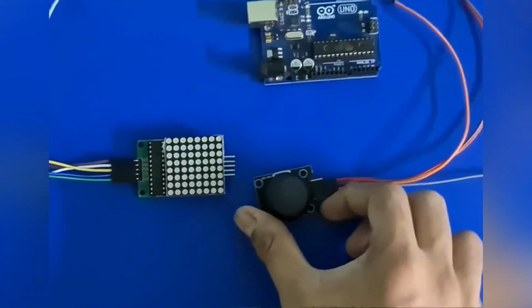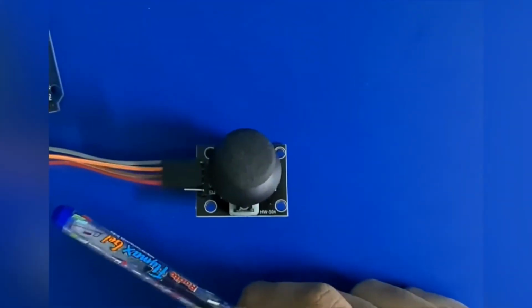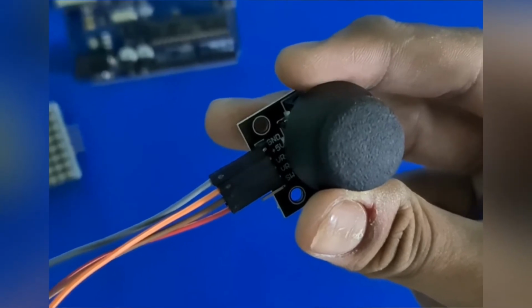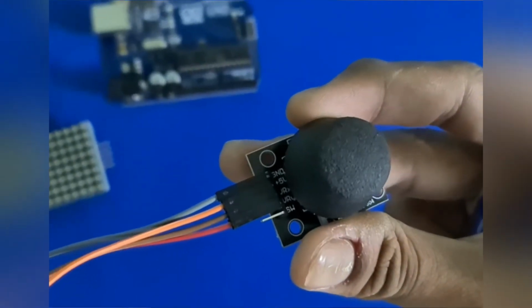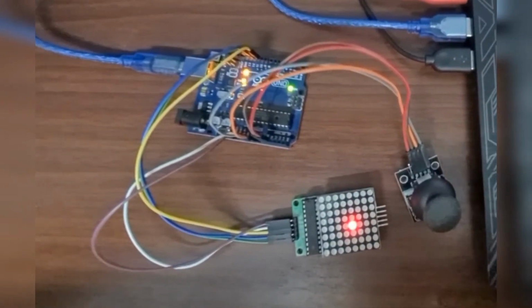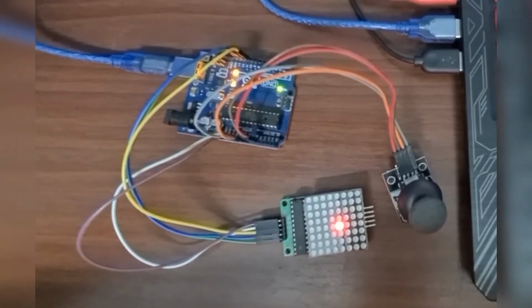Now, coming to the joystick module. There are 5 pins here, but we only need 4 of them. So if you notice over here, there is 1 pin for ground, 1 for the voltage, 1 is for the x-axis control, and the other for the y-axis control. We don't need the SW. Okay, so I finally connected my Arduino with my 8x8 matrix display and the joystick module.